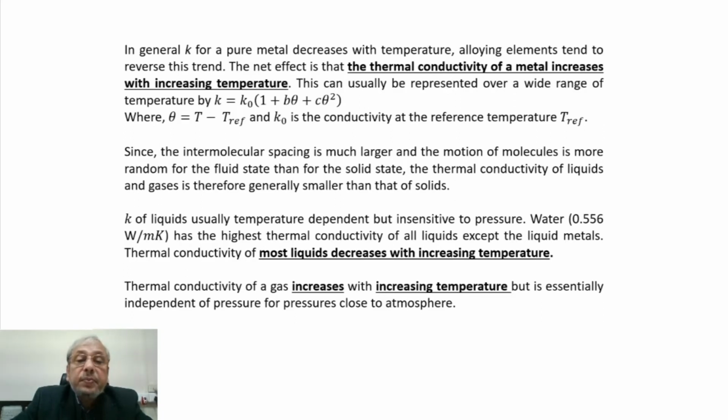Since the intermolecular spacing is much larger and the motion of molecules is more random for the fluid state than the solid state, the thermal conductivity of liquids and gases is generally smaller than that of solids. Thermal conductivity of liquids is usually temperature dependent, but it is insensitive to pressure.